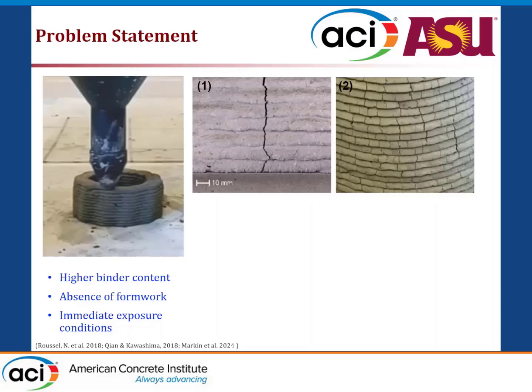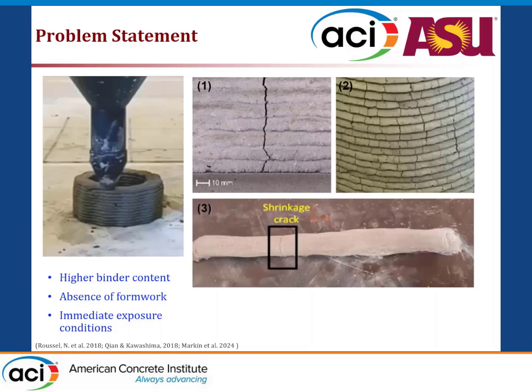Now, there are different problems with it. It might be an aesthetic problem, in the sense that you don't want to see a printed element cracking like that. Second, in terms of durability, you will see more chloride ingress and moisture ingress in these printed elements because of the cracks. The other is the final mechanical properties. Because there's already a crack, there's a stress concentration point. Now, if you put it in compression or flexure, it's just going to give you lower strength than you expect. So design-wise, shrinkage is important.